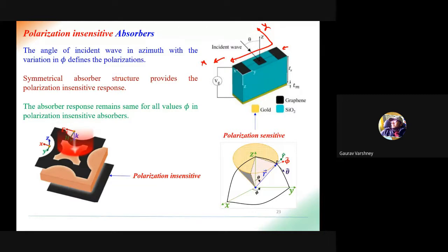Along the x-axis, the dimension of this unit cell is larger, L1. Along the y-axis, it is L2, and L1 is greater than L2. In fact, the resonator size is different along the x-axis and y-axis. So this unit cell will provide a different effect for Ex and a different effect for Hy. This means it will affect the incident electromagnetic wave components Ex and Hy differently.